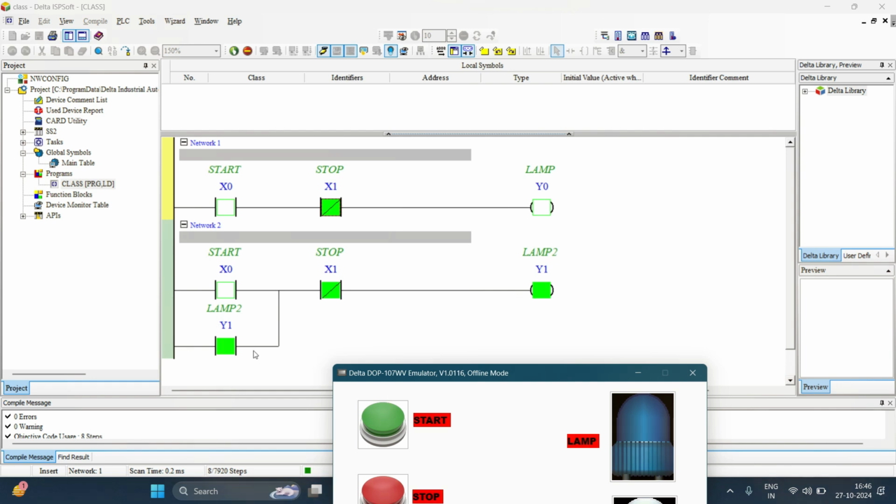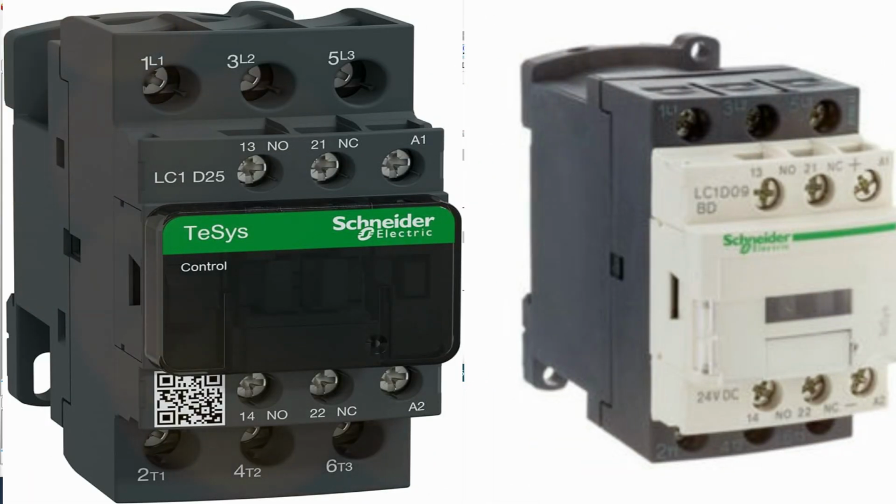This is what we call hold on. In wiring they normally say hold on, and for us in PLC, we normally consider it as latching. I use the output signal here to bypass the signal over here.